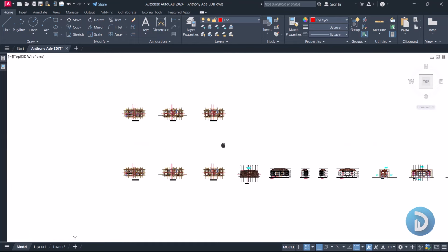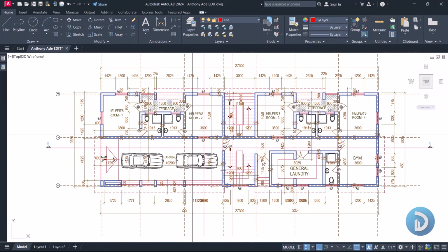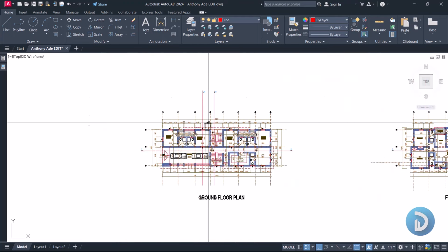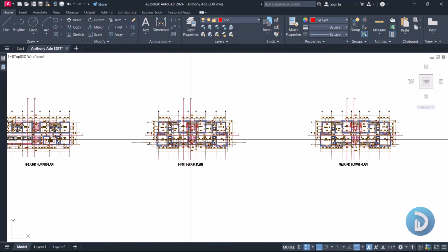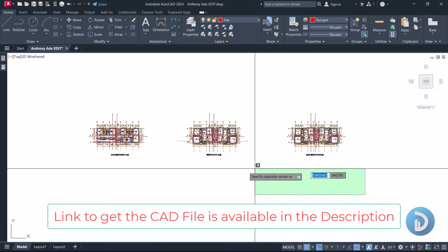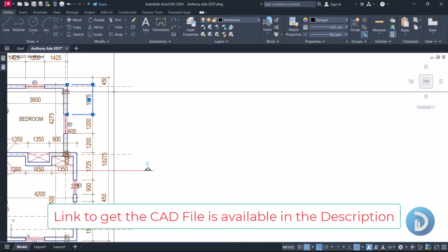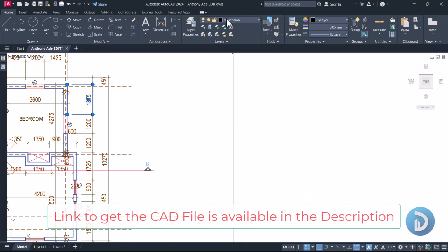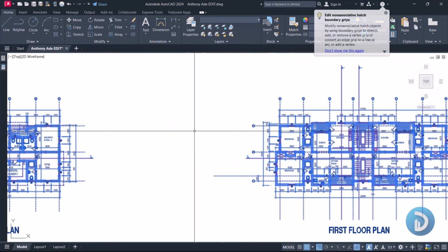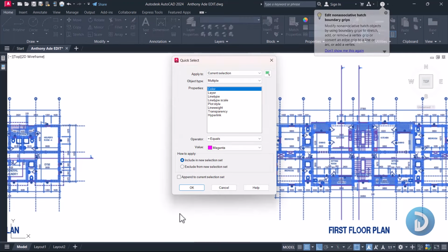Then let's go to the plan view, where we observe our grid lines. To see this drawing very clearly, I will appreciate we take out these dimensions, so we have just the block walls and their annotations. I will first select one of these dimensions, then observe the layer. This is under the dimension layer. I will select these three drawings, right click, then use my quick select tool to select those dimensions.